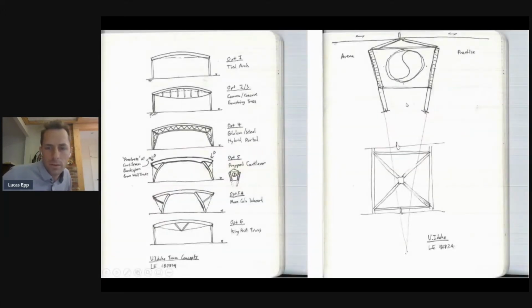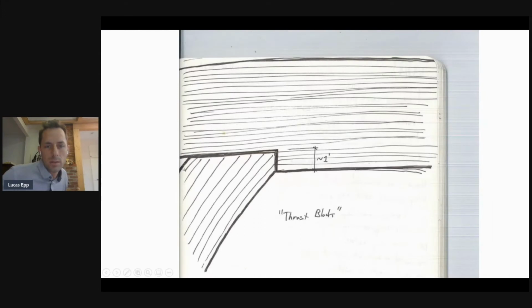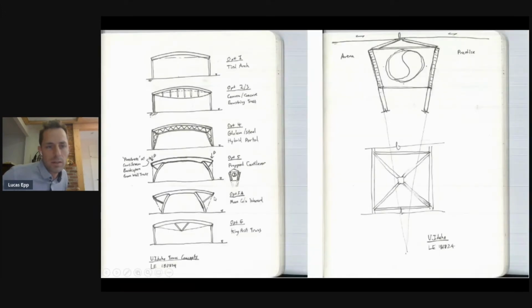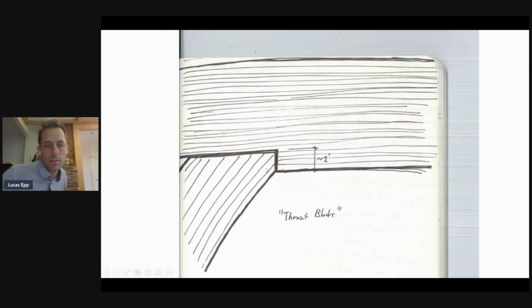And there's a big giant span in the middle where we're spanning these trusses over top of a practice gym and allowing the practice gym to be connected to the main span. So this was a really interesting structural challenge, creating this basically portal frame, prop cantilever portal frame is what we ended up doing, which basically has these columns thrusting into these beams with a huge load, a massive axial load thrusting from the column into the beam.